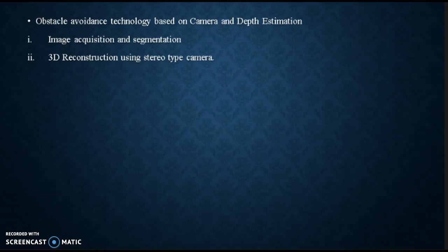For 3D reconstruction, the cameras and the robot reference system can be chosen such that the two cameras are displaced only along the x-axis of the robot coordinate system. In an ideal case, this system of equations provides the intersection between the two lines, starting from the cameras' origins, passing through the points on the image planes and reaching F. However, since disparity estimation, angle measurement, and pixel quantization introduce errors, these lines may not intersect at all.